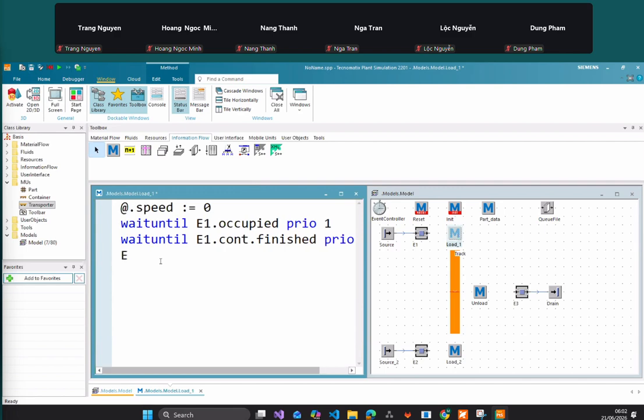And then after all of the conditions are fulfilled, you just move the part inside of the E1 to the transporter. I can try add here because the method load1 is connected to the truck, and the transporter triggers the method when it hits the end of the network exit of the truck. So it means add now reference to the transporter.